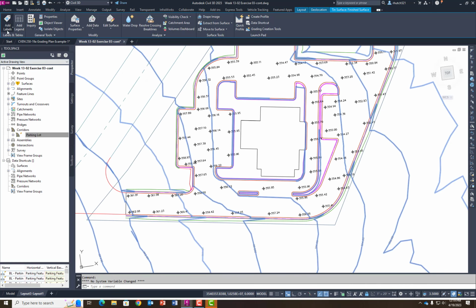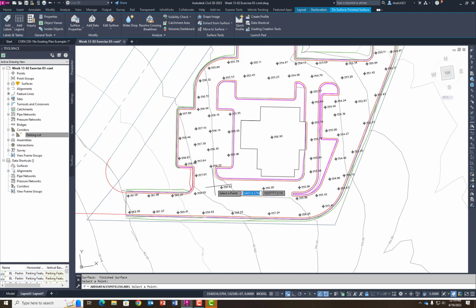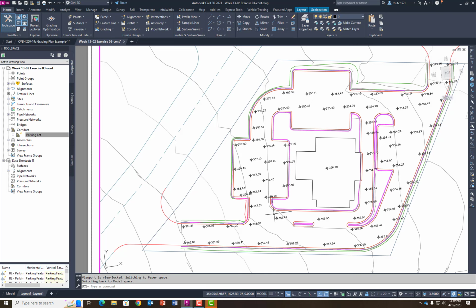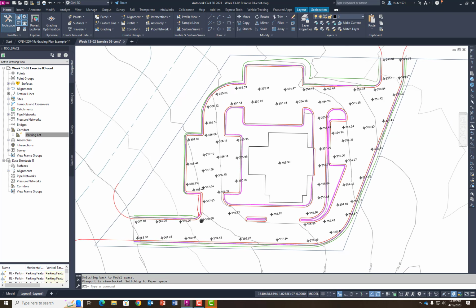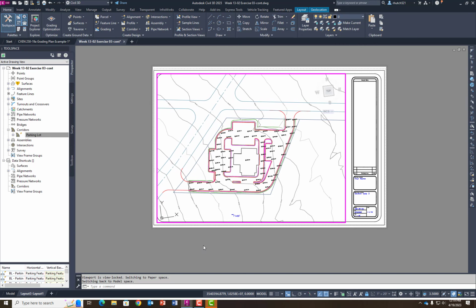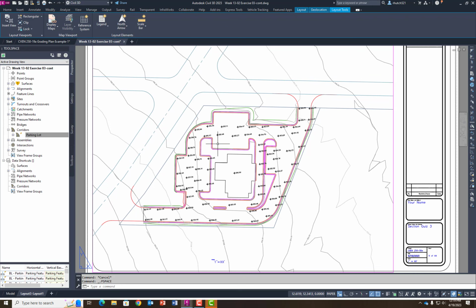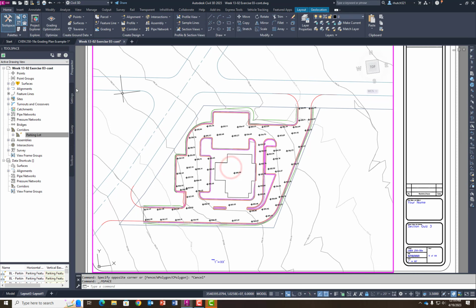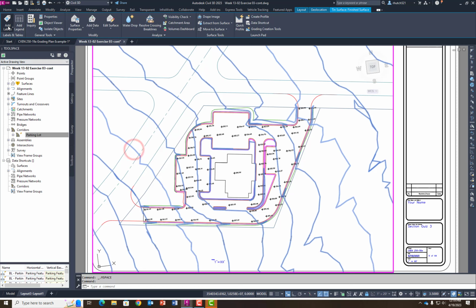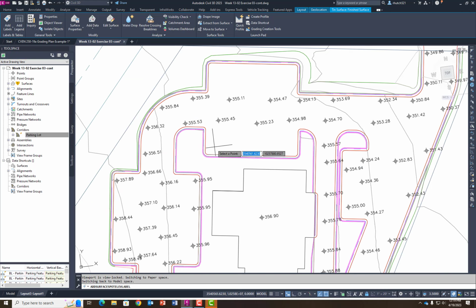And then one other thing that we definitely need to add is we've got to know what the elevation of our pad is. And so that is how we would set up our surface. That would be some of the primary stuff that we would do. Of course, we'd add in our scale, we'd add in our north arrow and things like that. And then this is the basis. I want to add a few more right here. This is the basis of what we want in our design.